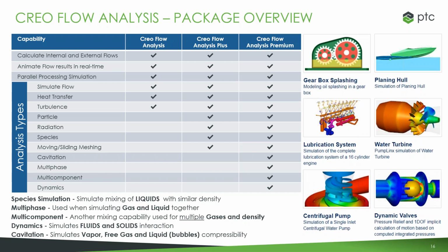And I think the question here, Bill, is can condensation be addressed in a heat exchanger with water entrained in steam? I think so. First off, we are capable of doing multi-phase analysis. This is liquid and gas. What you typically would do there is treat the water droplets as particles. I think you basically pretend they're solids. And you can indeed model particle streams, and the size and density of the particles are taken into account.